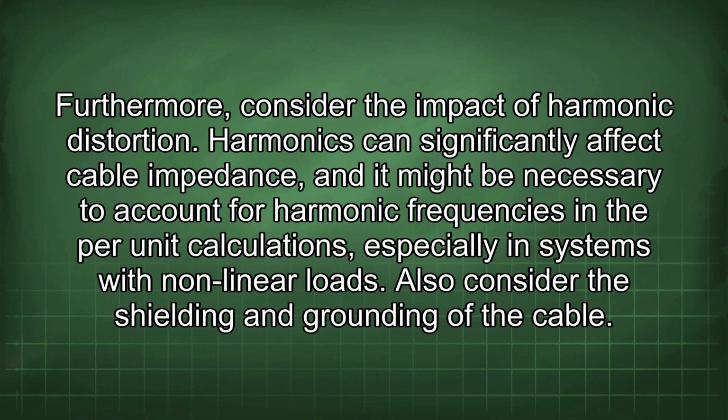Furthermore, consider the impact of harmonic distortion. Harmonics can significantly affect cable impedance, and it might be necessary to account for harmonic frequencies in the per unit calculations, especially in systems with nonlinear loads.